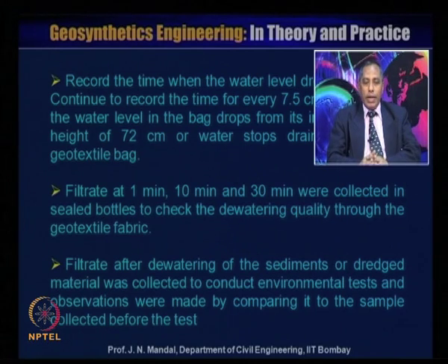Now, filtrate at 1 minute, 10 minute and 30 minute is collected in the sealed bottle to check the dewatering quality through the geotextile fabric.